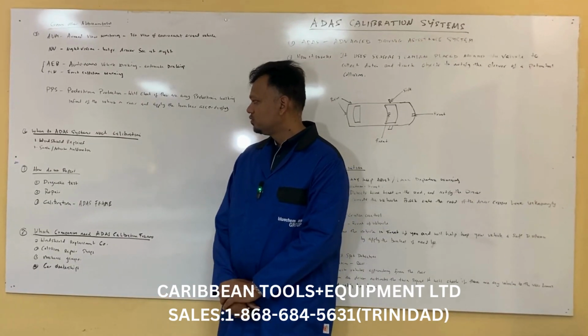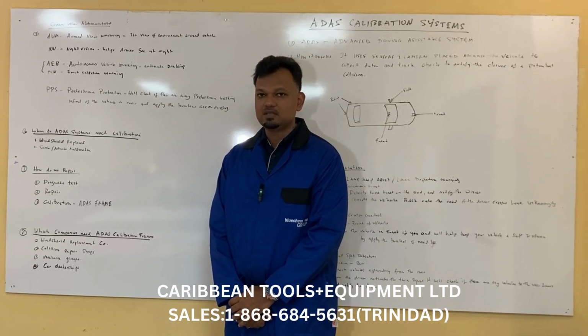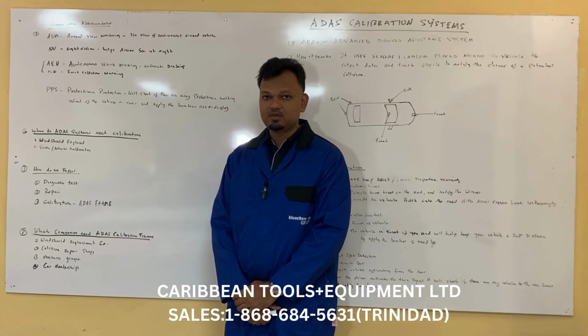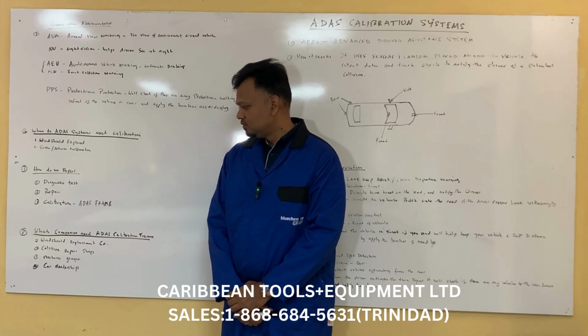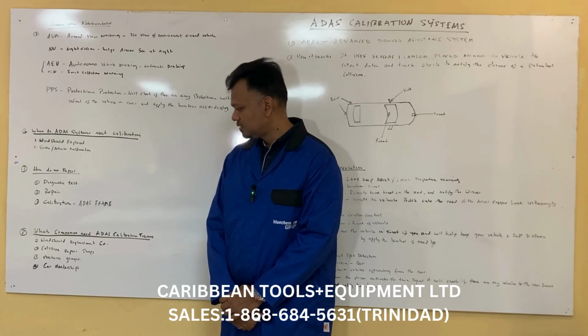So how do we repair? Well, the first thing we need to do is a diagnostic test to determine what part of the ADAS system needs repairing. We carry out the repairs, and then using an ADAS calibration frame, we recalibrate the system. So which companies need ADAS calibration frames? Windshield replacement companies, collision repair shops, mechanic garages, and car dealerships.